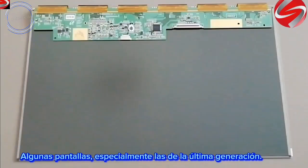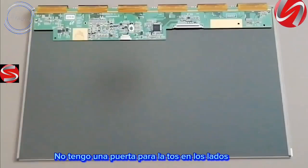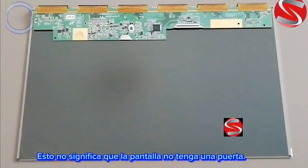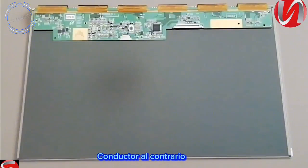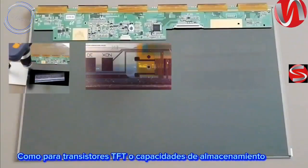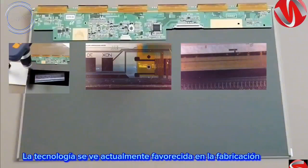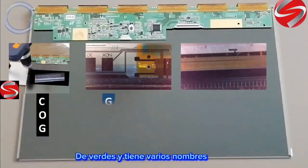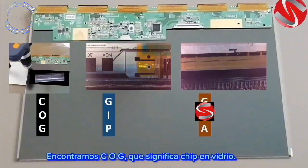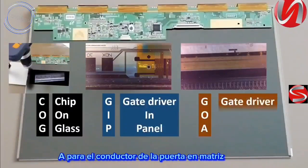Some screens, especially those of the last generation, do not have a COF gate on the sides. This does not mean that the screen does not have a gate driver. On the contrary, the chips exist and they are integrated directly into the panel as for TFT transistors or storage capacities. This technology is currently favored in the manufacture of screens and it has several names. We find COG, which means chip on glass, GIP for gate driver in panel, or GOA for gate driver on array.